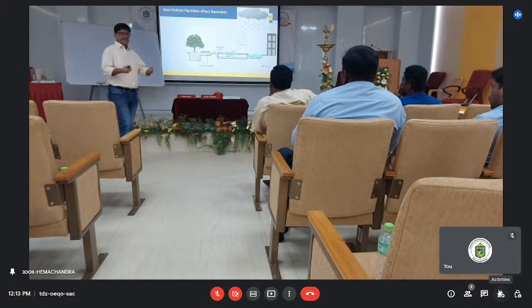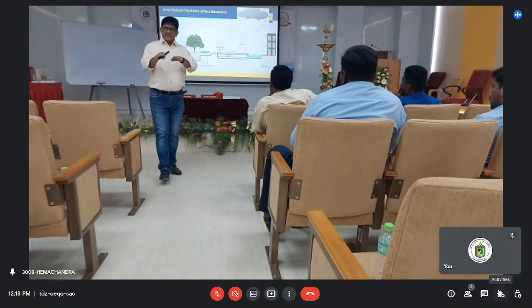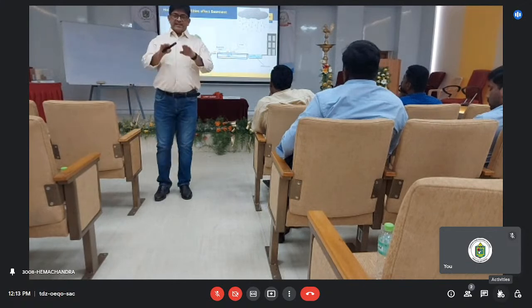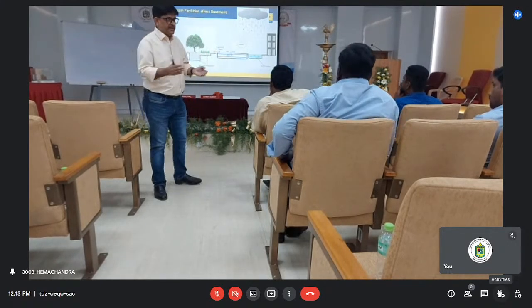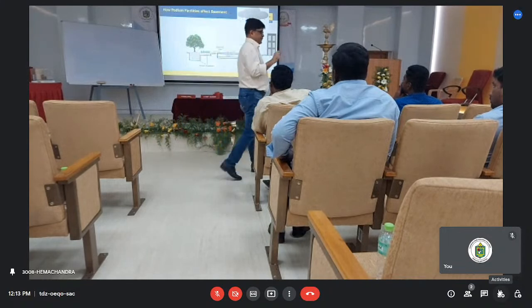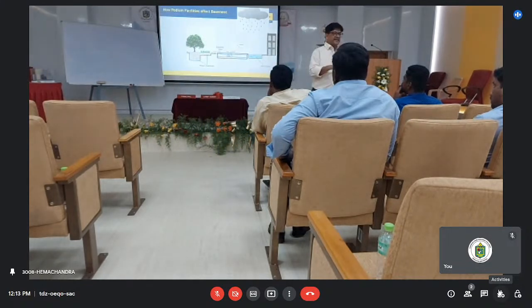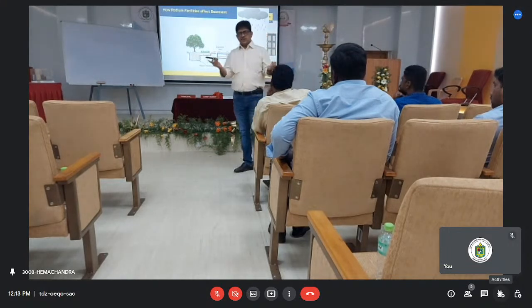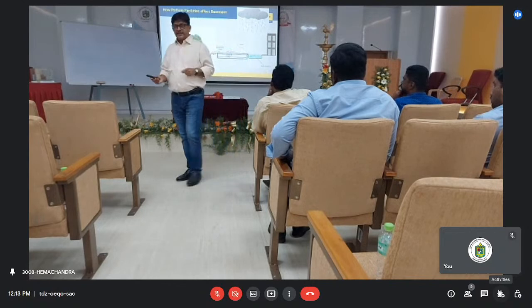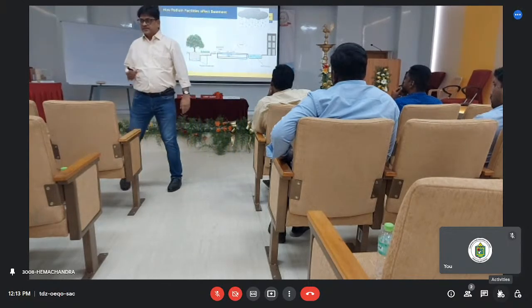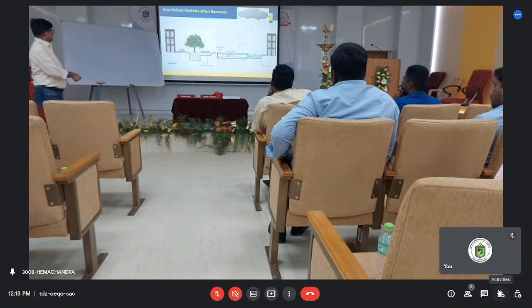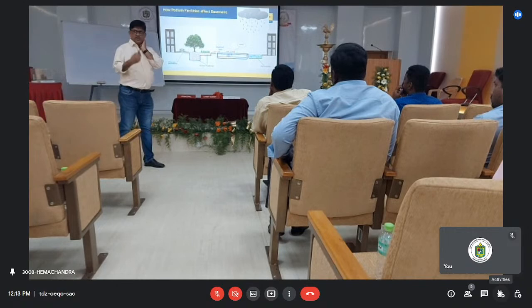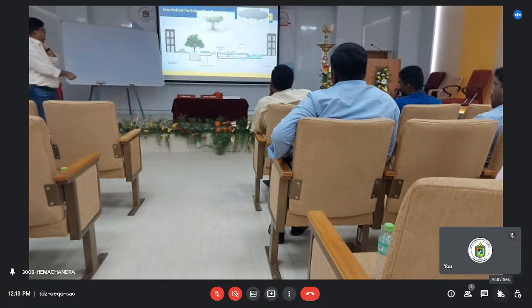There will be movements continuously. If you do not take care of the expansion joint rightly, with the right material and right treatment, then with time, because of wear and tear, the sealant goes off. We normally go for a sealant, but once the sealant gets torn off, water can easily enter, right? And finally the vehicular movement. So all these functional facilities are already giving a lot of different troubles, which ultimately are the movements we have already talked about.